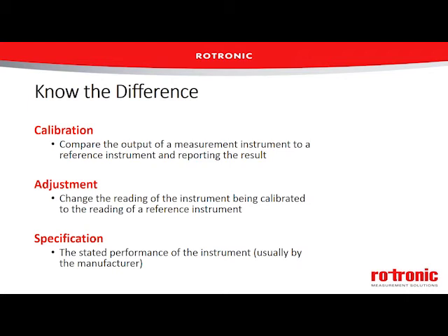First, the term calibration. This is where you compare the output of the measurement instrument to a reference instrument and report the result. The confusion comes in because the service offered by laboratories is called calibration, and many times that includes a calibration and an adjustment.